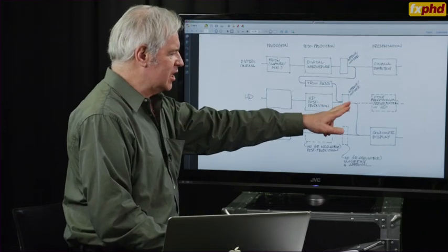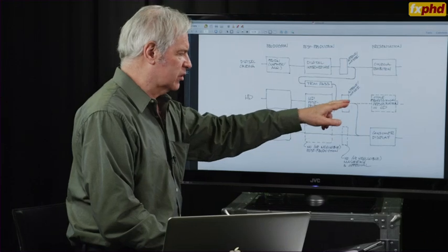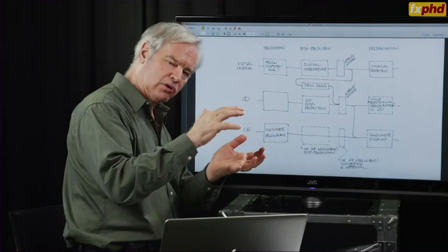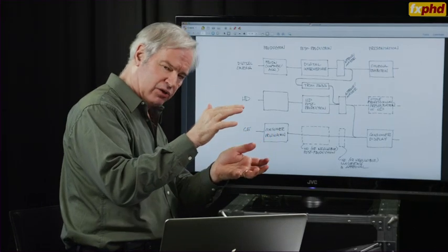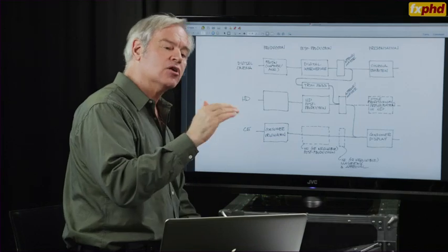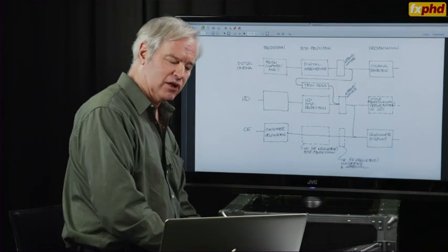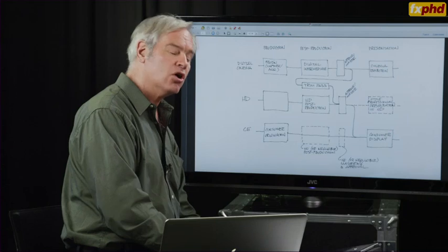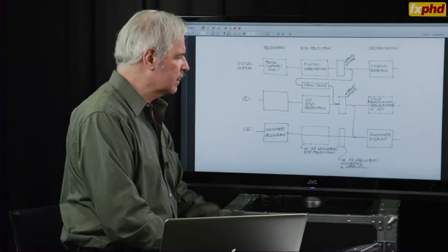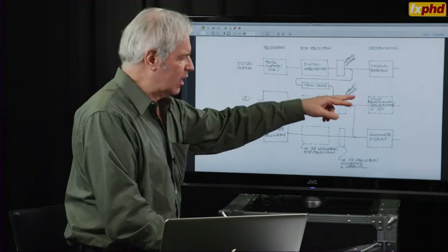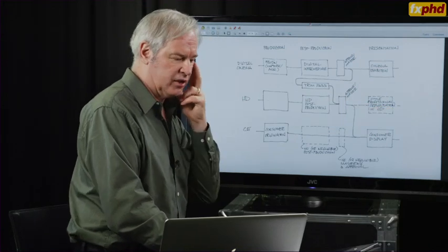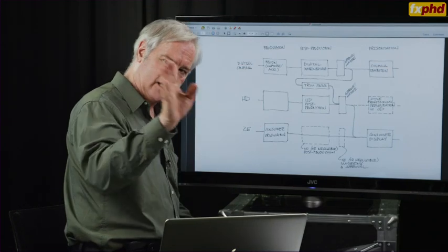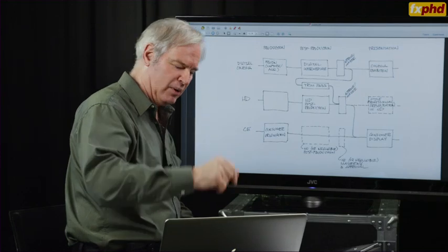For HD, the expectation is you'll come out in 709 gamut, which is a little bit smaller than P3 gamut, but standard for HD, and standardized just in 2011, gamma, or the exponent of the power function, 2.4. And that assumes that we're coming out into a display environment of about 100 candelas per meter squared. Your monitor calibration experts locally will know about that.